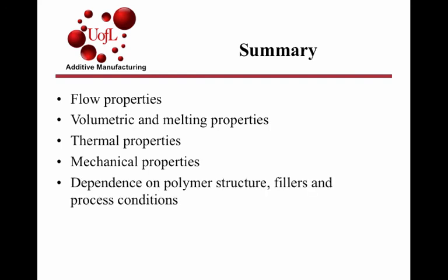We saw that we can alter the polymer structure or the nature of the filler or the amount of filler to affect these properties, not only in the final product, but also to take into account different effects on process conditions, printability, if you will. The design equations that we covered allowed us to design materials with specific properties for specific endpoints with specific predictable processing characteristics.